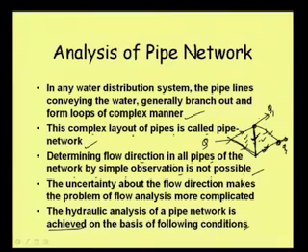Then another interest is that, say this diameter, we do not know what the diameter should be. If we fix a pipe of a different diameter, then although we need water of say Q1 here, it may happen that this Q1 water is not available there, and as such we will not get the required amount of discharge at that point. That we can achieve by adjusting the diameter of the pipe. So those issues are important, and analyzing those things and designing the pipe network all come as a part of hydraulic analysis of pipe network.